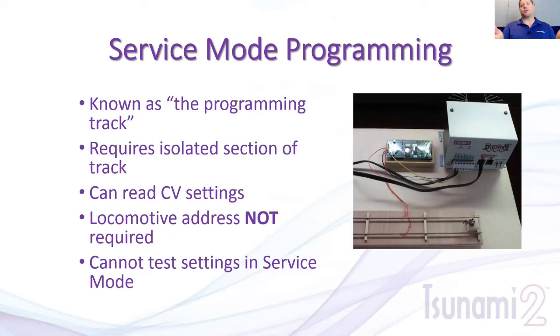So if you've got a programming track booster, one of the SoundTraxx PTB100s, you'll have those visual indicators, the lights on the PTB that will tell you where the programming is, so you can actually see what's happening on the programming track. So you don't need to remove it, but it's not going to damage it if you put a decoder on there that requires or does not require a booster.